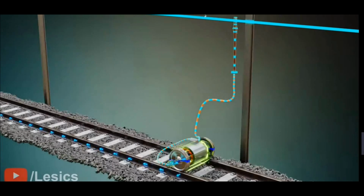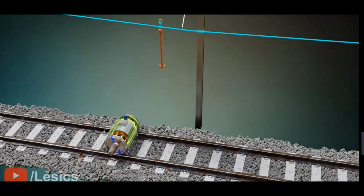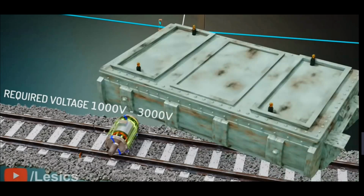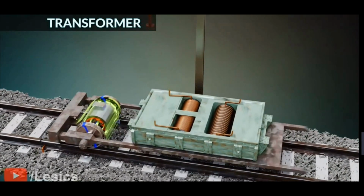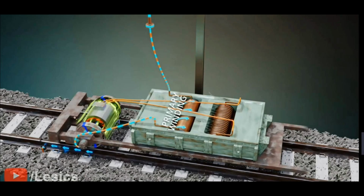Now, let's improve this design and make our train more functional. The voltage used in the overhead line is 25 kilovolt, which is a huge voltage. Motors require much less voltage to run. For this reason, we need to feed it to a step-down transformer, which transforms the voltage to the desired level. The power supply from the overhead line initially passes through the transformer's primary, and here, the circuit is completed due to the grounding. Because of the transformer's action, the current will be induced in the secondary winding and reduced voltage power is fed to the motor.